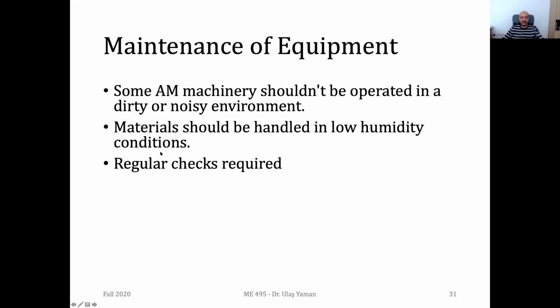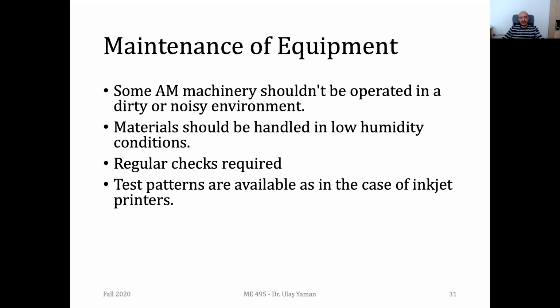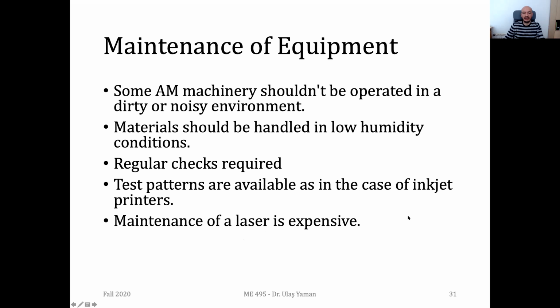So you may perform some regular checks on the material quality and on some parts of your additive manufacturing machinery. And from time to time, you may print some test parts and check whether your printing equipment is functioning properly or not. They're very similar to the test patterns we have in paper inkjet printers. And maintenance of the lasers is quite expensive, so you should be careful while you are using such laser-based systems.